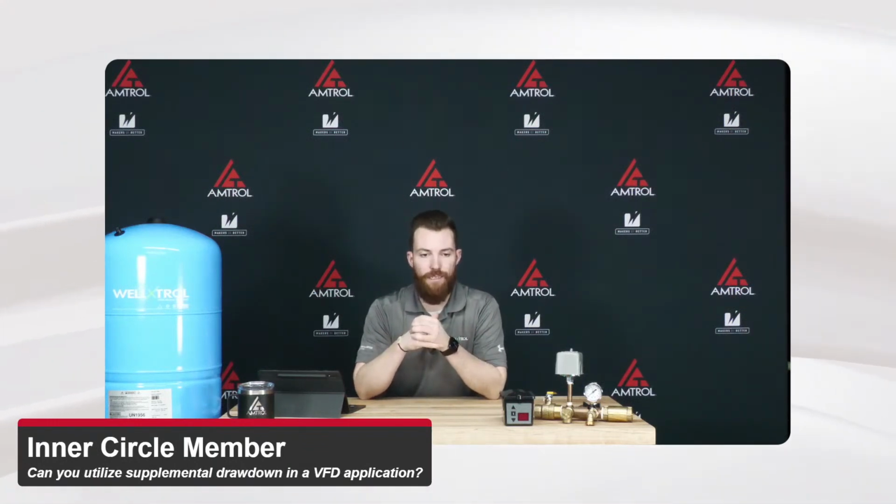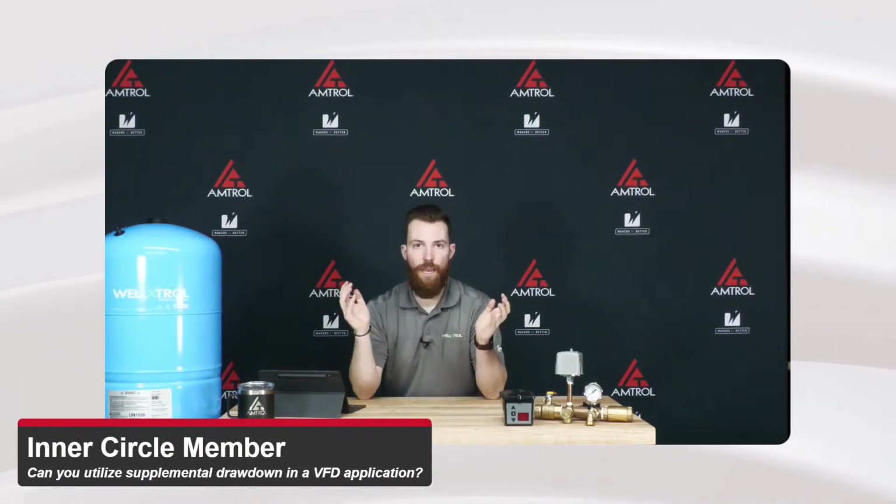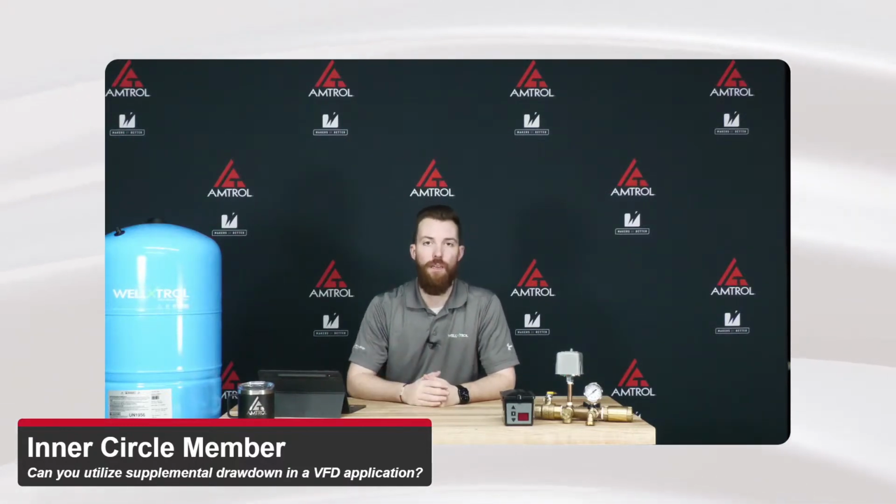So they'll have a desired downtime that they want on their system, whether it's 30 seconds, 3 minutes, a half hour, I don't know. They always have something they're aiming for to have downtime for their equipment, because that obviously helps their longevity. So they'll size a tank according to their expected flows and demands on the system to make sure we're meeting that specification. So it's used for that peak demand stuff.